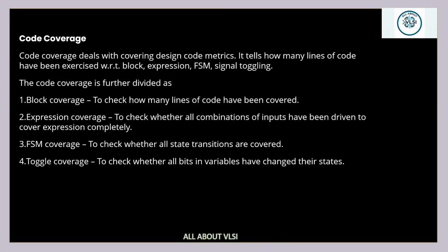Here also, in the case of SystemVerilog, I'm going to make sure that I have covered all the particular features or not. If I have a decoder-based RAM in our example, I have covered all the RAM addresses or not, or I have generated all the possible data, or I have generated all the address possibilities or not. I have covered all the test cases or not. I should have some kind of metric, right? That particular metric is nothing but my coverage.